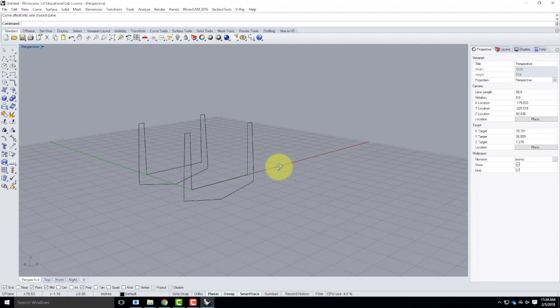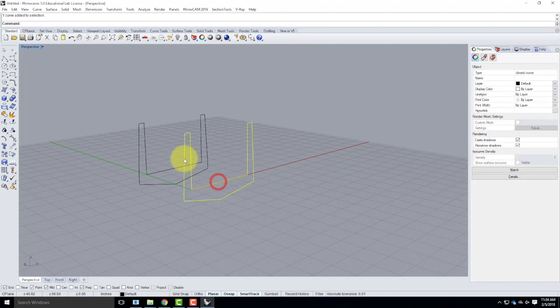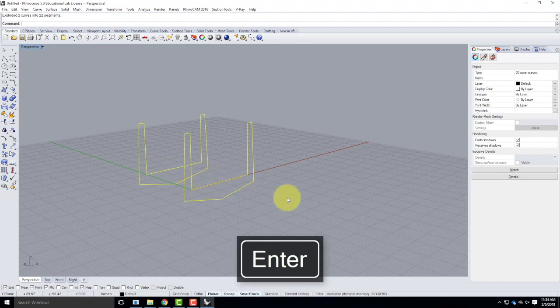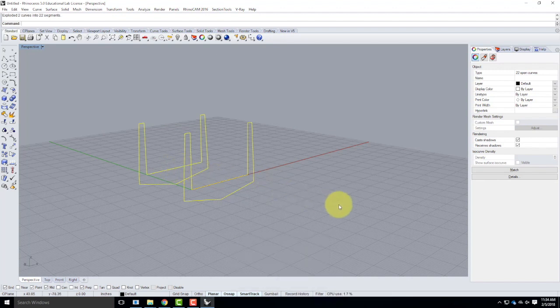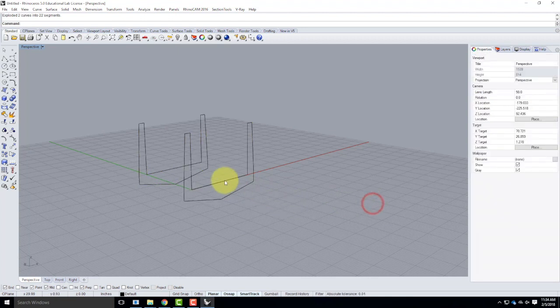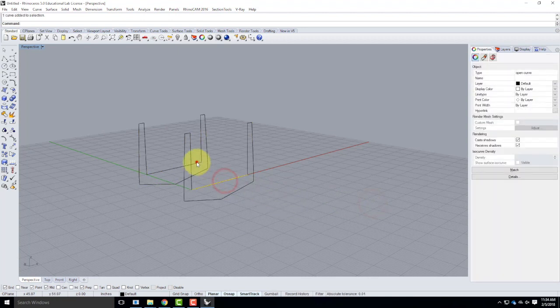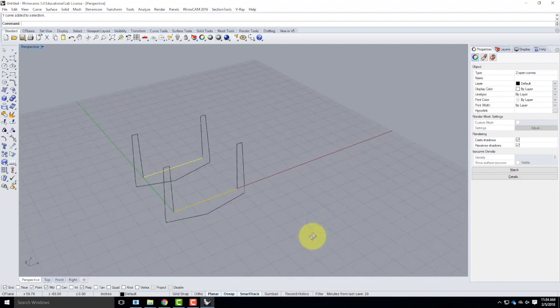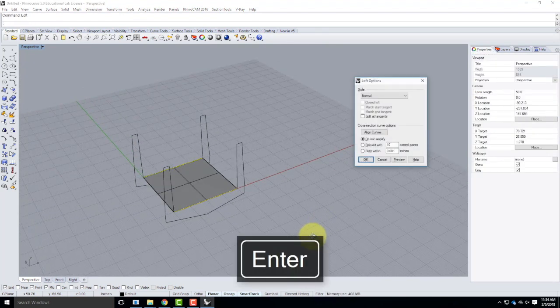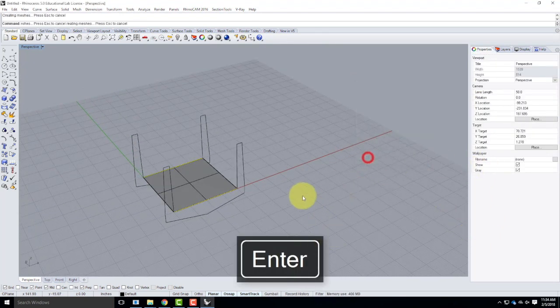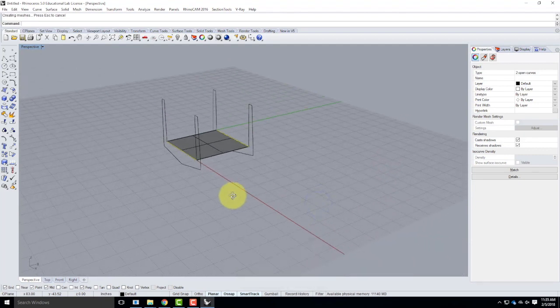Now on the directions, I told you to go ahead and explode these 2 parts. The truth is you don't have to, but it's good practice. So I'm going to go ahead and explode these. Not good practice in terms of you'll want to do it all the time, but good practice because on the loft command you're going to do this a bunch of times and get used to it. So essentially at this point I'll take the 2 opposing lines, so those 2, and I'll type loft. Default options are fine, and I've now created that first surface.